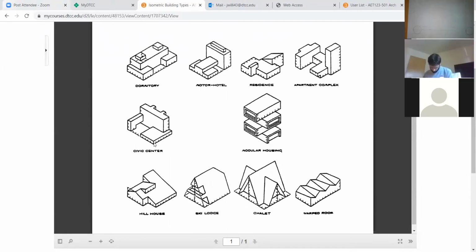each one of these ticks here represents 2 feet. And we know that we're going to be drawing the isometric view at a scale of 1/8 of an inch equals a foot. So you're going to establish this horizontal plane, and then this is your x-axis. Along the x-axis at 30 degrees, the length of this building is 2, 4, 6, 8, 10, 12, 14 feet at 1/8 of an inch scale.